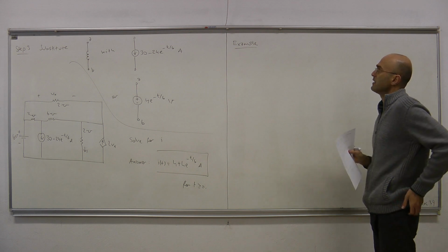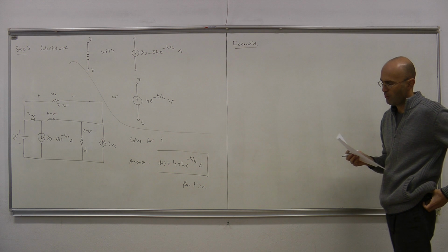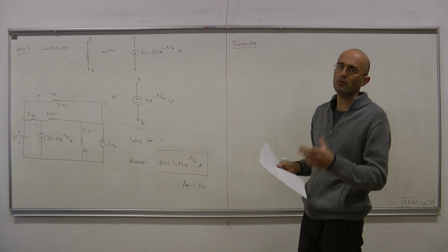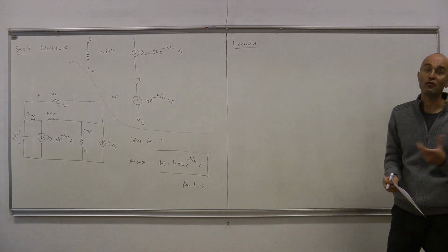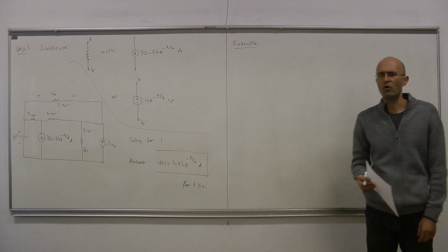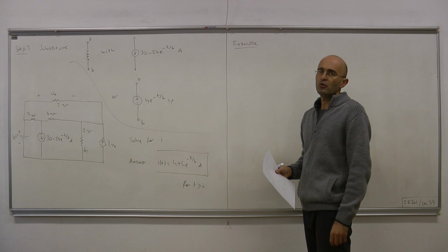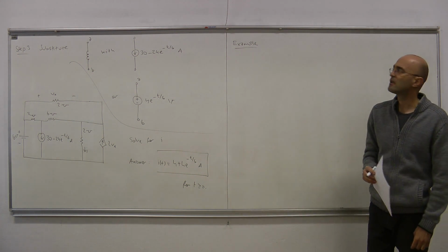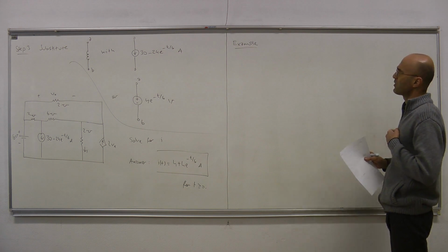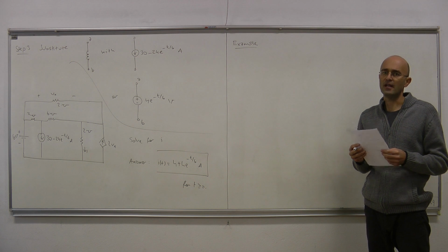So we're going to be dealing with, for the first time, more than one dynamic component. In general, if you have, let's say, 3 dynamic components, you would expect your circuit to be of order 3, meaning that the description will be through a third order differential equation, but in this case, because the topology is special, we will be able to work out the answer using our first order techniques.